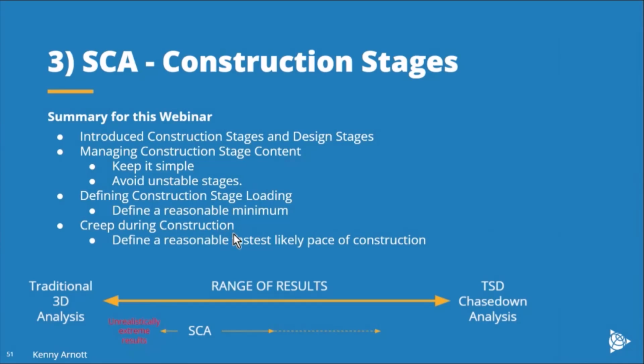And then a similar sort of thing applies for the creep during construction. As long as you define a reasonable fastest likely pace of construction, then you'll move the results away. So the more load that you're prepared to say, I can rely on that level of load, or I can rely on the construction not being any faster than this, the bigger you can make those things, the more that you move this result away from that result, and eliminate some unrealistic extremes.